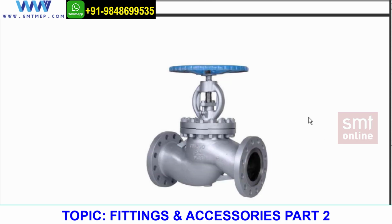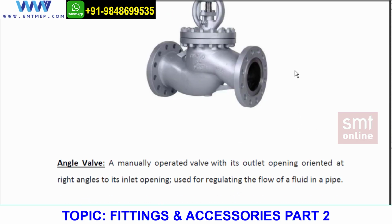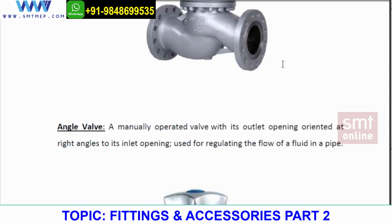So this is a regulating valve. That means I can adjust the flow as per my requirement. For example, I have a pressure gauge at the outlet and I need a pressure of 10 psi. If I'm getting 20 psi, I can adjust by pressing this, I mean opening or closing. I mean rotating clockwise for closing, or anti-clockwise for opening. So I can regulate the flow as per my requirement. Okay, so this is generally a regulating valve.